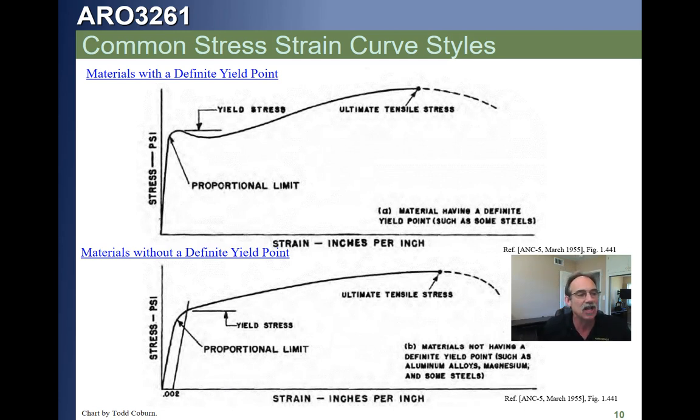What we're going to do is take the slope of that curve initially, the stress-strain relationship, that slope of stress over strain of the initial part of the curve, and we're going to slide it over till it goes through the 0.002 inches per inch strain. That's called 0.2% strain, right? Because 2% would be 0.02, 0.2% is 0.002. That's a common mistake made by students, by the way. So we're going to take that initial slope of the original stress-strain curve, and then we're going to slide it over through the 0.002 inches per inch strain, and wherever that new curve strikes the original stress-strain curve, we're going to call that point the yield stress. Okay? That seems kind of arbitrary, but actually there are reasons that we'll discuss as we're going forward of why that is valid and reasonably accurate, and it keeps things simple.